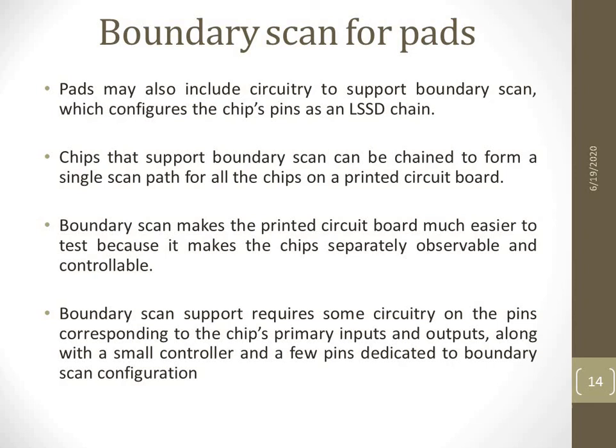So these pads, which are located as a boundary or circle on the chip, can be used for boundary scan, or for testing that particular chip. I hope you have understood all these things from Unit 4, that is floor planning and testing: how to plan and place the devices, how to supply the clock and the power, and some of the parameters related to floor planning and placement.